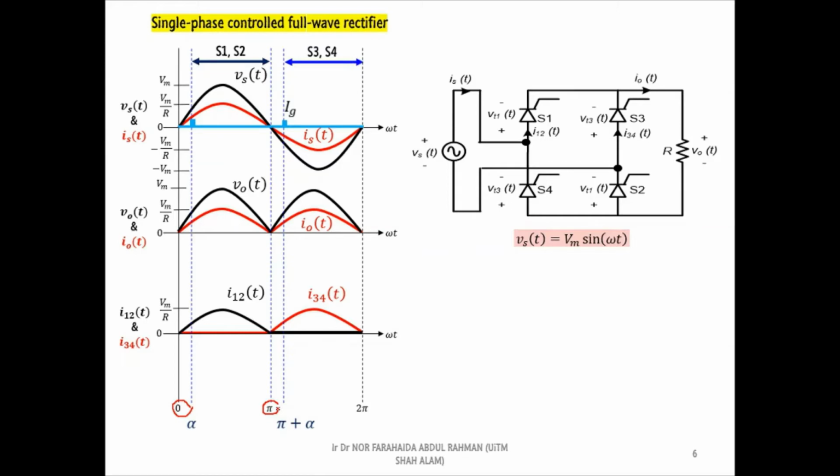As discussed earlier, all voltage and current waveforms except the supply voltage will be chopped before the control signals. For the full wave rectifier, it happens at the starting of both positive and negative half cycles of the supply voltage waveform.